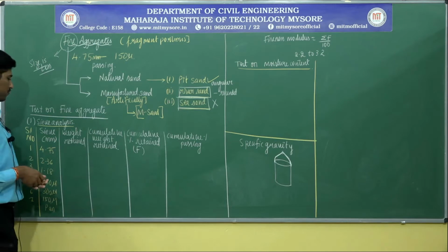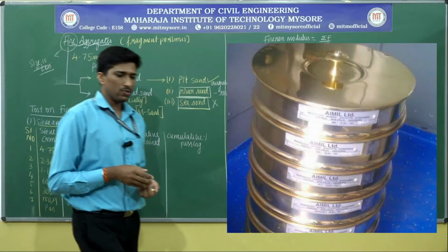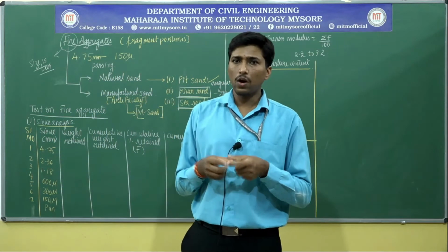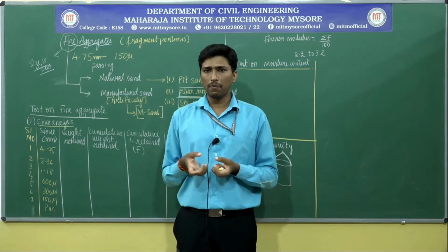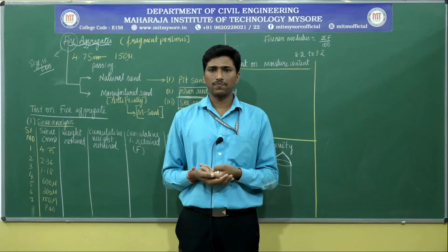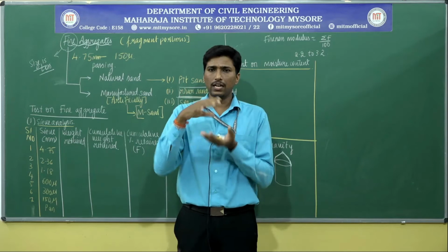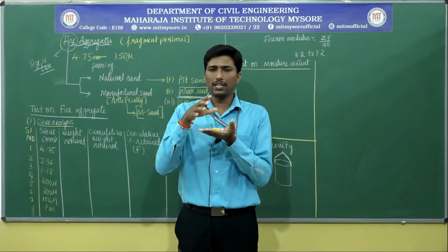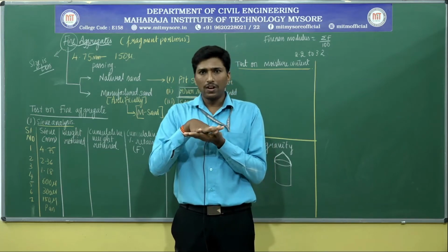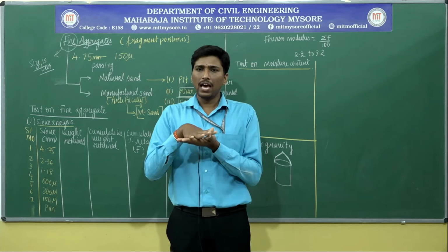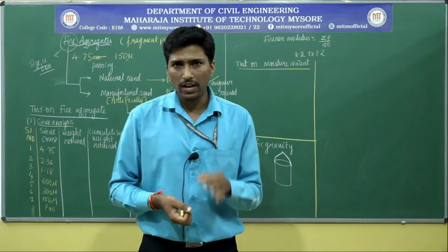Sieve analysis. If you observe carefully, the term sieve refers to the openings or net-like appearance made on a hollow pan, where the openings are made so that the ingredients or grain materials pass through it. Sizes which are bigger than the openings are retained there itself. Hence, here the procedure is used to determine the fines content.